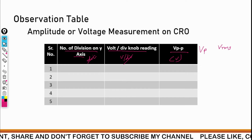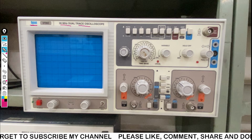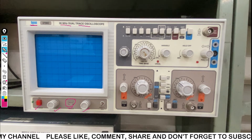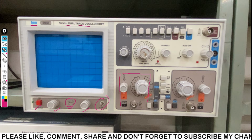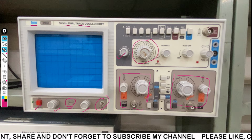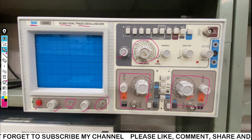Right. You can see this is an AppLab CRO, a 30 megahertz dual trace oscilloscope. We have the on-off button here, intensity, trace, focus. This trace is nothing but a rotation button. Here is a test point. Then this is the X-Y channel actually, and this is the X channel. You can see here the time per division knob, and the level button to adjust the signal.